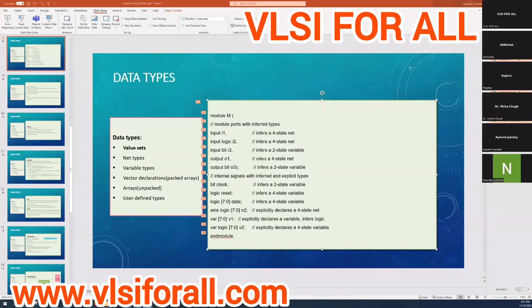And the other thing is, it's also not exactly C++. It's a combination of Verilog and C++. Verilog is used to model hardware, and C++ is software. And SystemVerilog is a combination of hardware and software. The hardware part is mostly used for design, and the software part is mostly used for the testbench. Because ultimately we want to synthesize the design, right? We want to create silicon out of it. So we cannot use C++ because we cannot synthesize it.